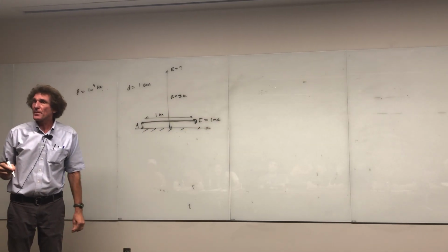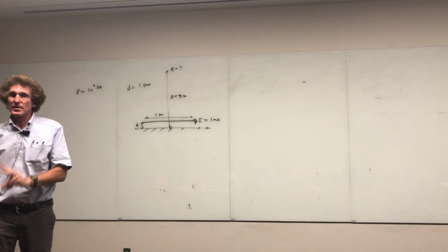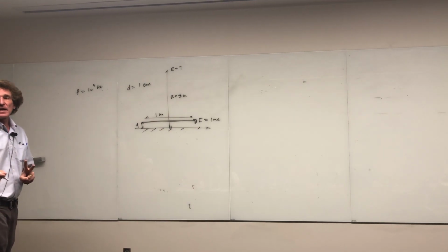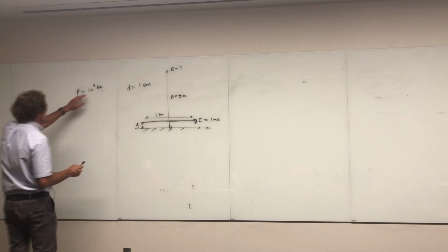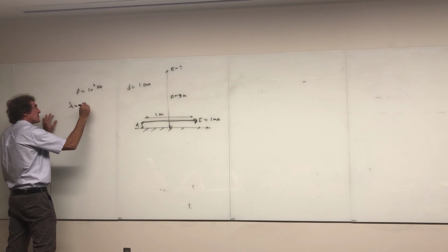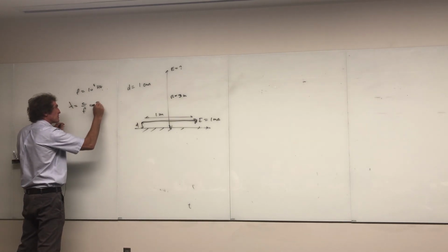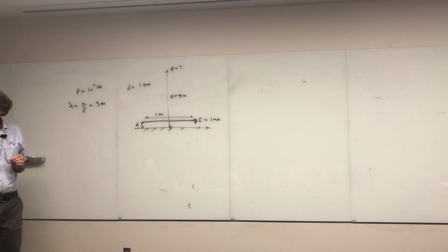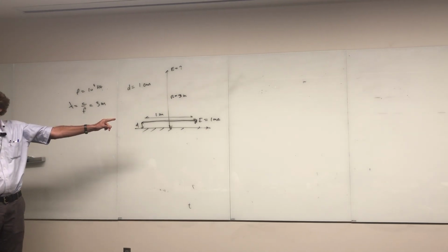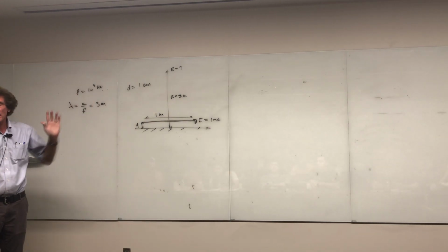Now, here's the one thing that's a little blurry here. Normally when you do a problem like this, the first thing I tell people to do is determine the length of the antenna in wavelengths. So if this is 10 to the 8th, lambda, the wavelength would be c over f. c is 3 times 10 to the 8th, over 10 to the 8th is 3 meters. Everybody follow me? Now this is 1 meter. This is in that gray area. 1 meter long is not much less than a wavelength, but it's not a half wavelength either. Do you all follow me? It's in that gray area.